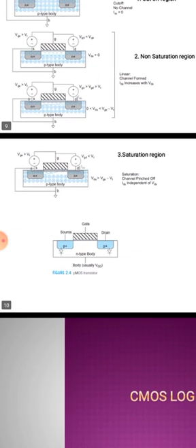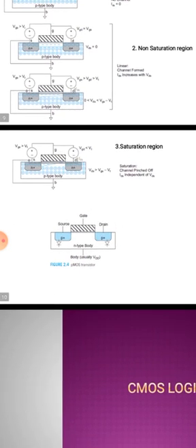In a PMOS transistor, the important thing is that the body or substrate is generally held at high potential. If the gate is given a high potential, meaning a positive voltage, the source and drain junctions are reverse biased. As we know, between source and drain there are two reverse-biased diodes present internally, so no current flows. Hence the MOS transistor is in the off state.